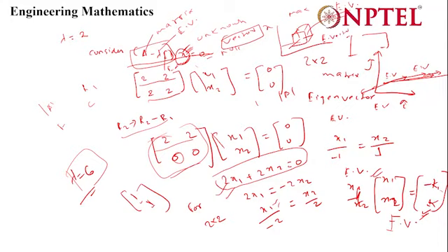You have studied the stress tensor also, right? One example of this is the stress tensor. When you calculate the eigenvalues of your stress tensor, they are called principal stresses and principal directions. That is the maximum stress at some plane. That is why we get infinite solutions. Okay.